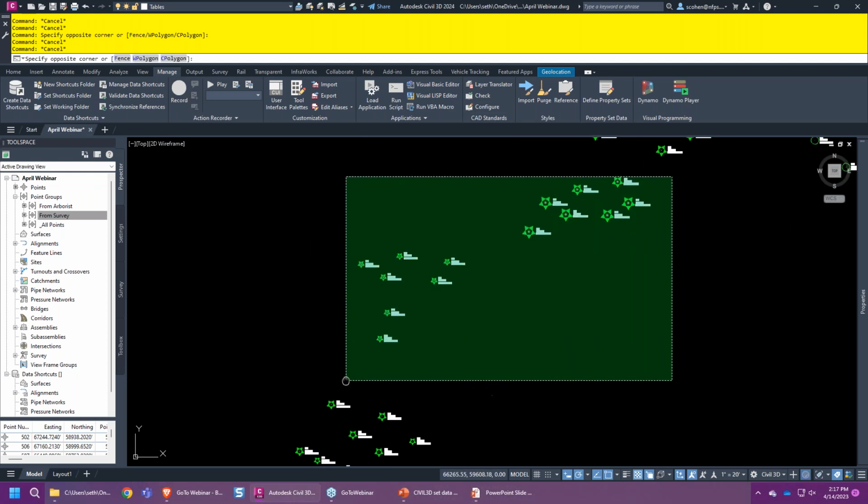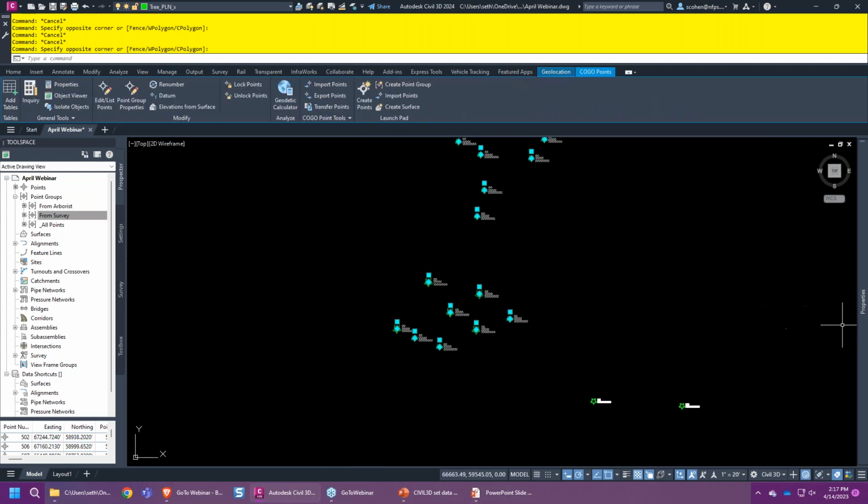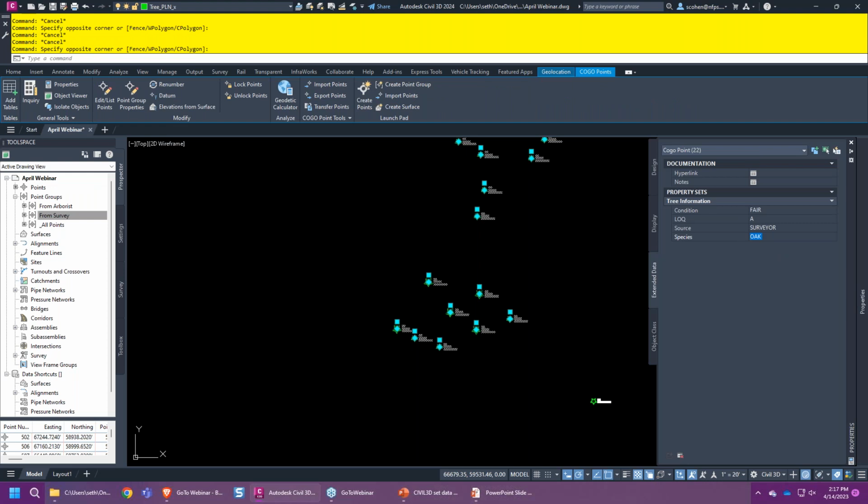And then what you can do is simply select the entities that you want to change. And yes, you would have to go in and change them yourself. If you put them on different layers, which I did not, the description key is just controlling one layer for trees, all right? But you could actually put them on their own unique layer, do a select similar, right? And then change them in this way as well.